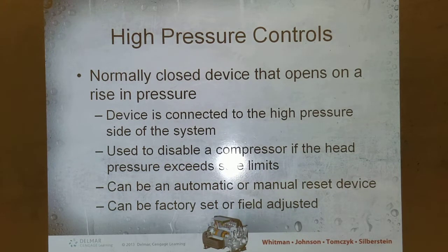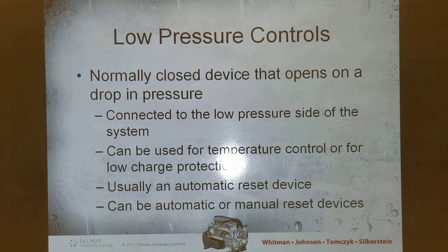All kinds of different high pressure controls. Most of the time, a high pressure control is going to be a safety, and the good ones are going to be adjustable. You can buy factory OEM head pressure, high pressure cutoffs that screw right into the system. But it'll be up to you, a matter of preference.